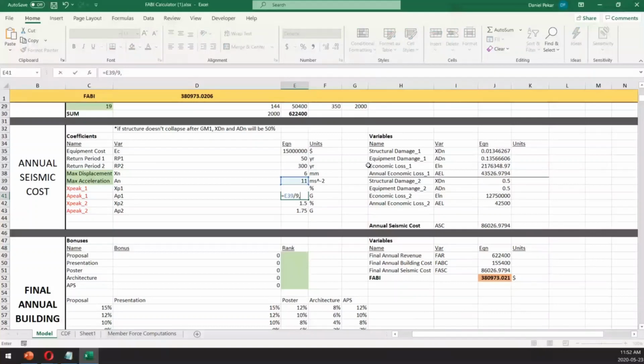What it's going to do is calculate the drift, which is the proportion of how much your tower moved to the side divided by the height of your tower. So you can see it's our number here divided by 60, which is how many inches tall the tower is, divided by 25.4 because there's 25.4 millimeters per inch, and then times 100 to get percent. And then we convert meters per second squared to Gs, which is just divided by 9.81.